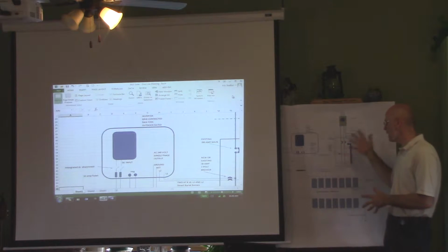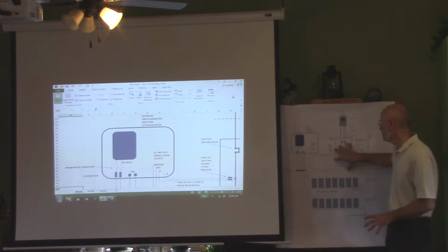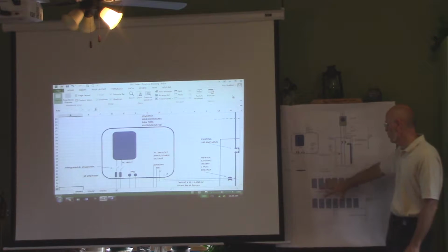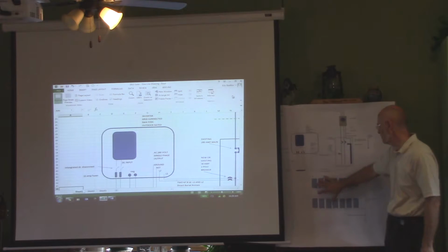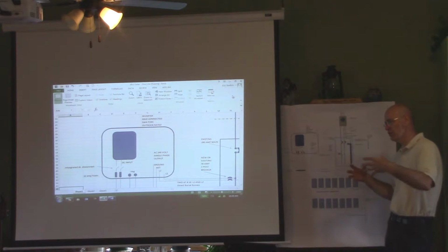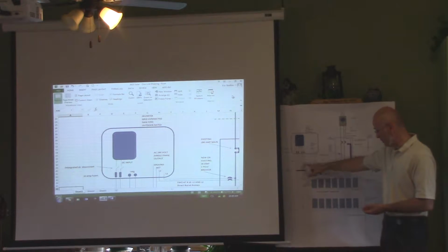This is a simple diagram that gives you a plan. Where you physically put this doesn't matter electrically, unless you're really a long distance away, like hundreds of feet. Where you put this doesn't matter to this diagram. It can be 50, 60 feet from wherever, as long as you're not creating super long electric runs where you're lowering your voltage, because copper does have resistance. Wires are copper, so you do need to overcome that. If you put this, let's say, 3,000 feet from this, which wouldn't make any sense, well, then you're going to have a voltage drop to overcome on that wire.